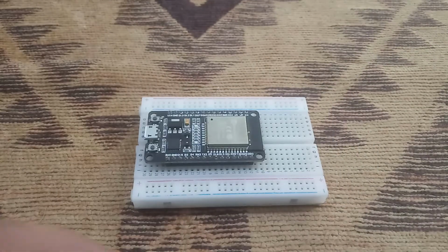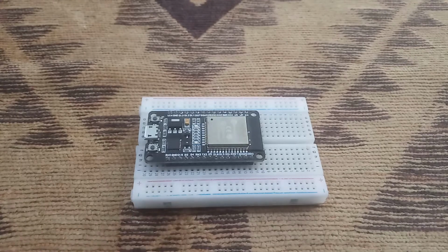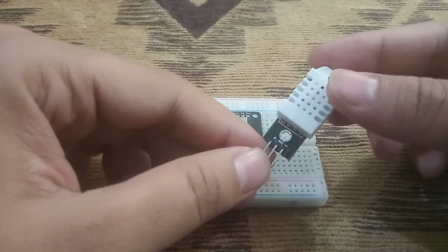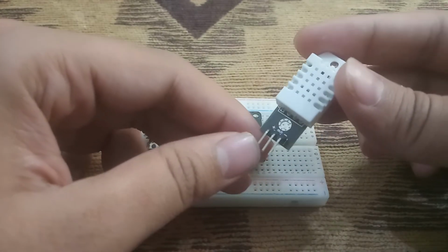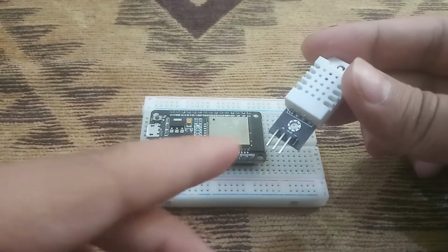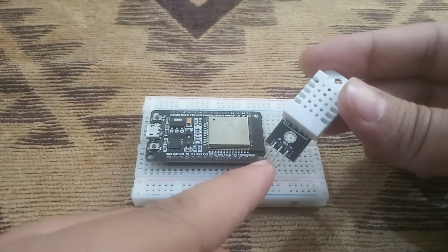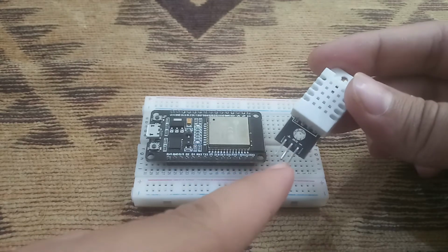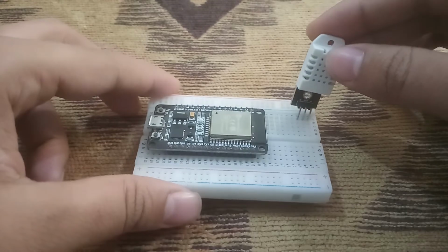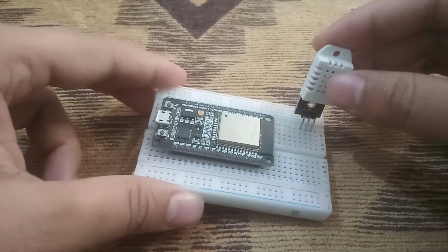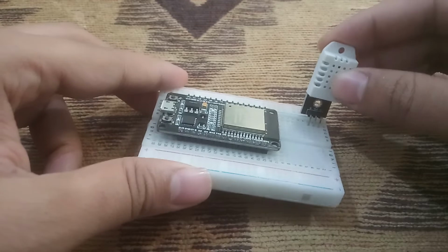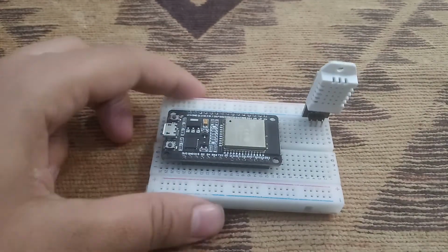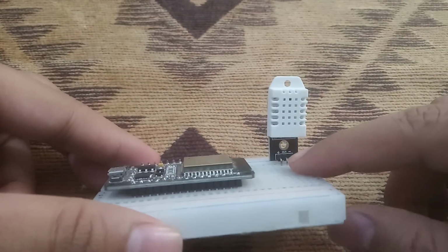Now the last task is to fit this sensor. So this sensor consists of 3 pins. This is the new version. The one is the positive terminal, the second is the output terminal, which is connected to D4 of the pin, and the third is the ground. So it is very easy to connect. I am connecting it here in the line of A. Okay, and the first pin according to the number written is positive.